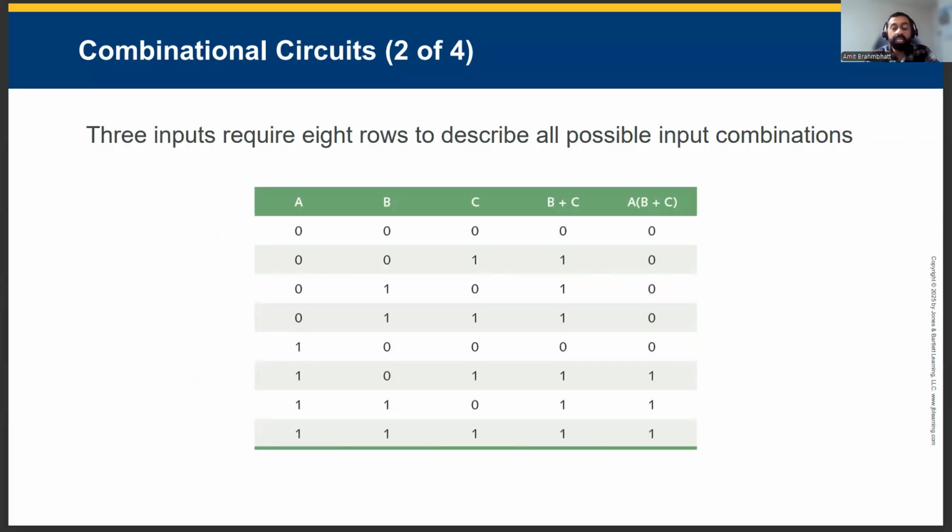When a circuit has three inputs A, B, and C, the truth table requires 8 rows to cover every possible combination from 000 to 111. Filling those rows forces you to consider all cases, and it's a great way to verify your diagram or algebra. If any row surprises you, trace the signal path through each gate to debug.